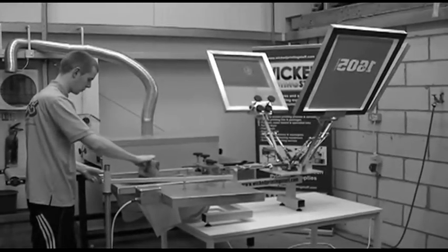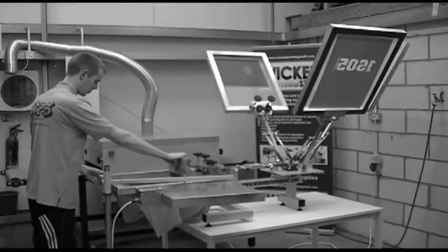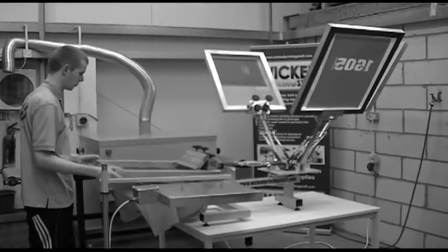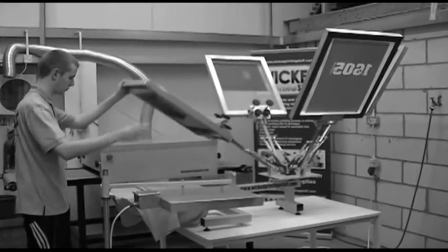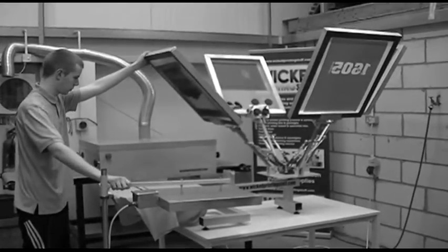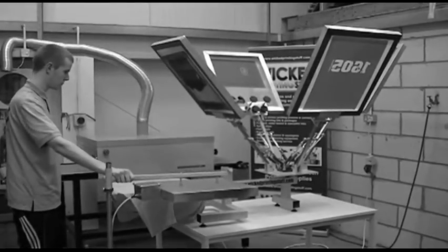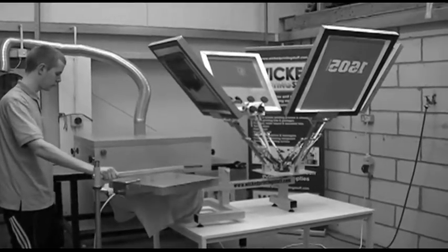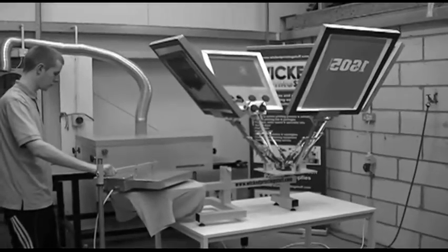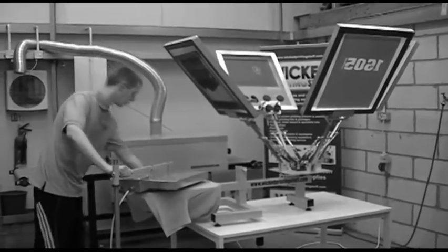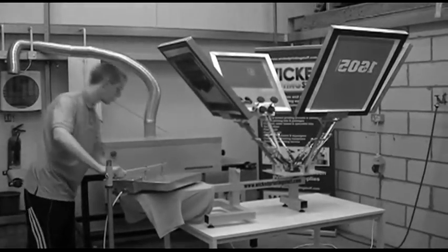If you are using a Wicked Printing Stuff flash dryer to cure your print, we recommend you measure the temperature of your print with a digital laser thermometer until it reaches the required temperature. In this instance, 153 degrees. Depending on the nature of your fabric, it is recommended that you break this up into intervals of approximately 10 to 15 seconds and repeat 3 to 5 times, as most garments cannot withstand such continuous heat in one go.